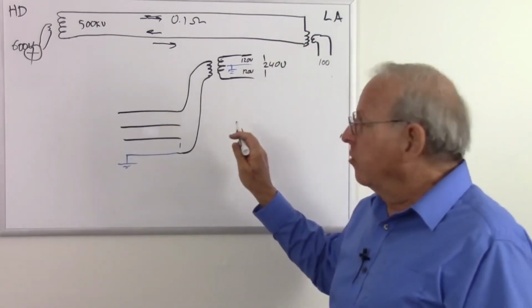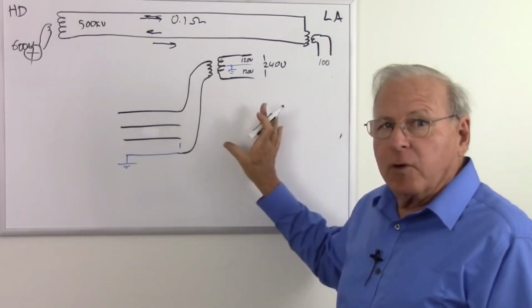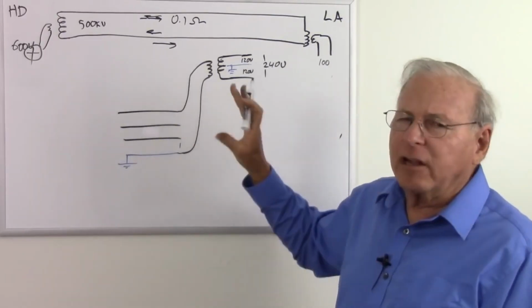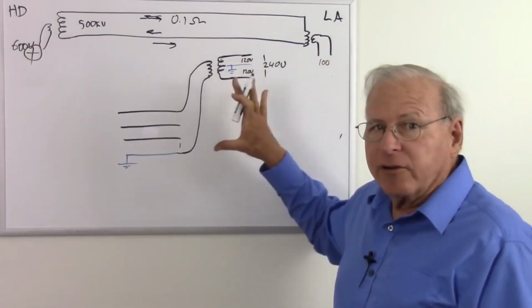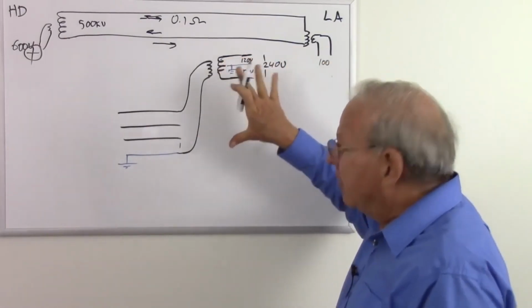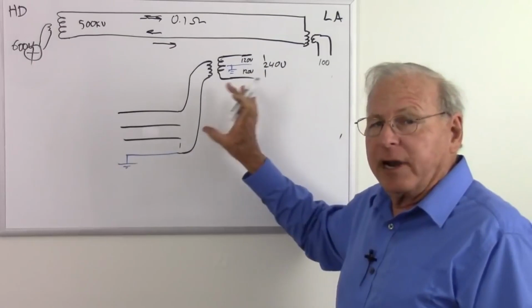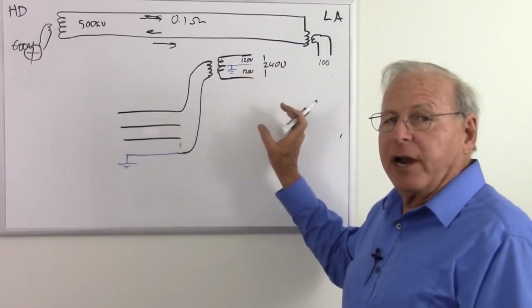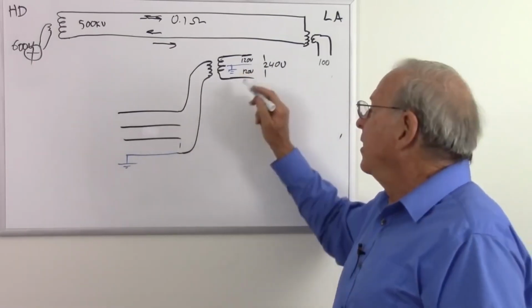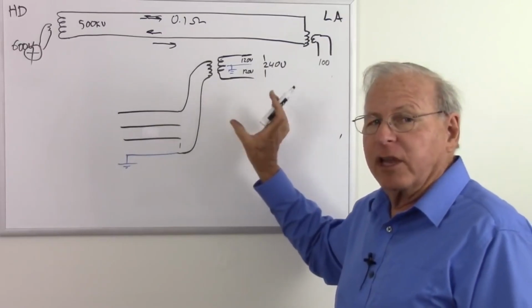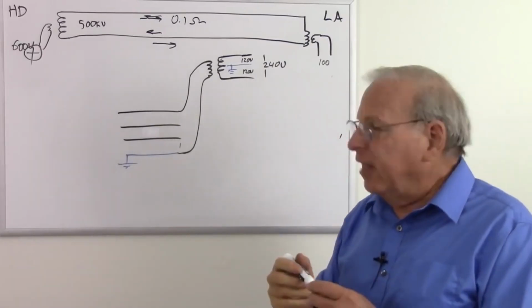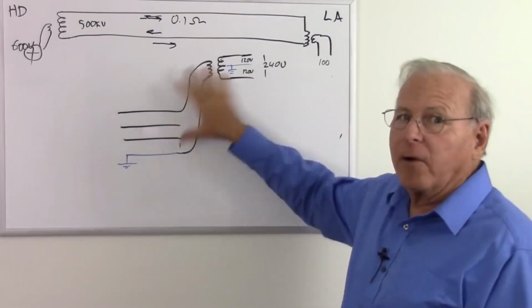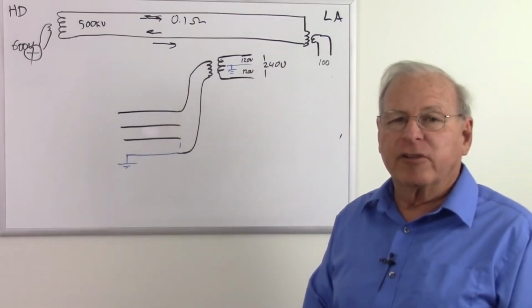And once again, that goes into a breaker panel. It might go to the same style of panel. There's another style too where the breakers just look different. The connections are different, but it's the same thing. Some breakers go to one phase and ground, other breakers go to the other phase and ground. And to get the full 240 volts, you have breakers that go between the two phases. So that's the basic idea of how we get that power off to industrial areas and to residential areas.